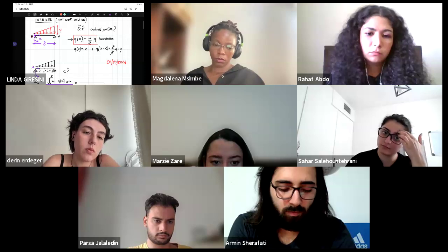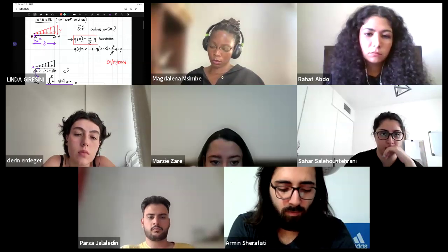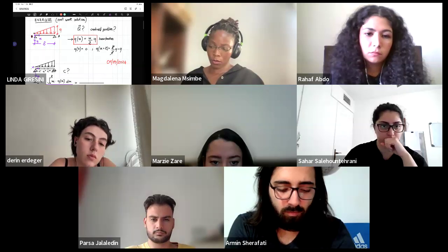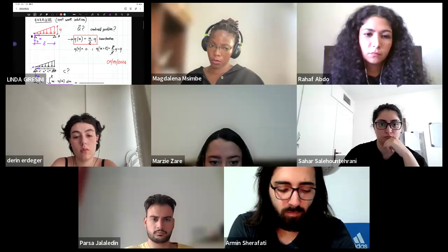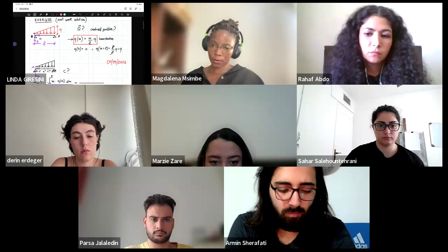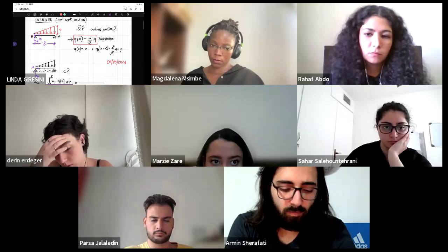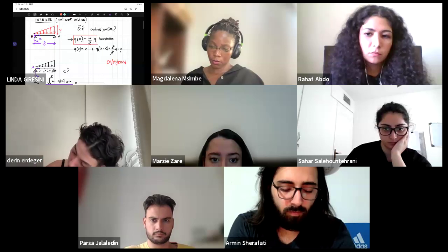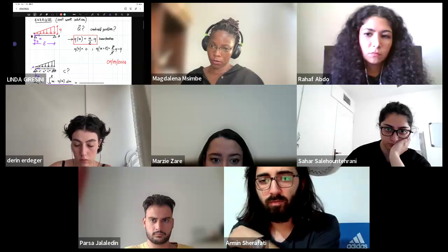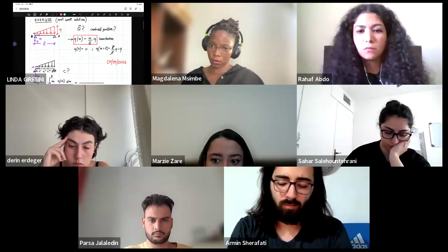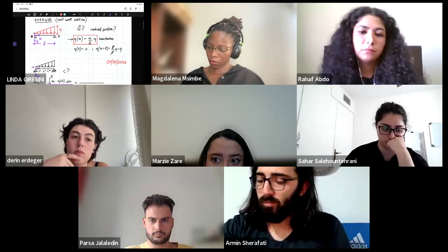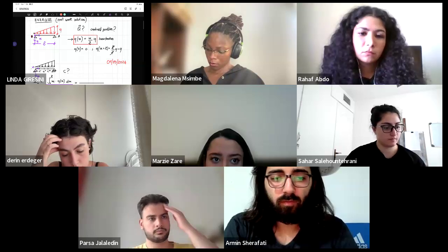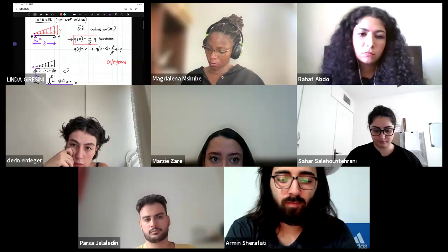Very important to know: q, small q, is expressed as, what is the unit of q, small? It's a force divided by length, because it's a line load. Also tomorrow there will be some questions. Yeah, correct, Orkan, thank you so much. But newtons are always a capital letter, never small, okay? Meters, yes. Also tomorrow there will be such kind of exercises. So if it's not clear that a line load is a force divided by length, please have a look at that, okay?